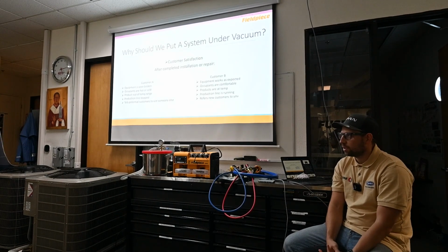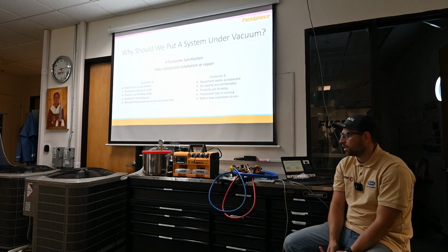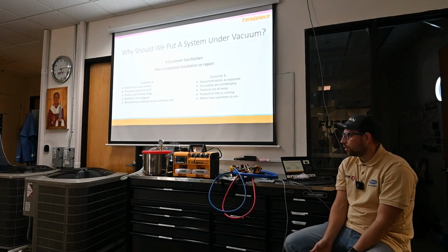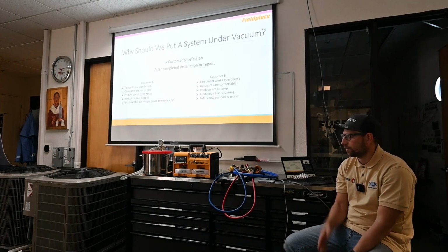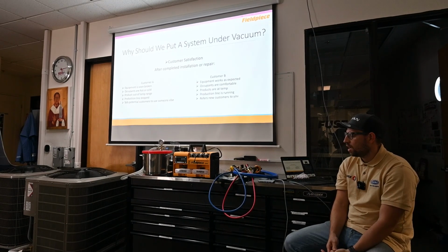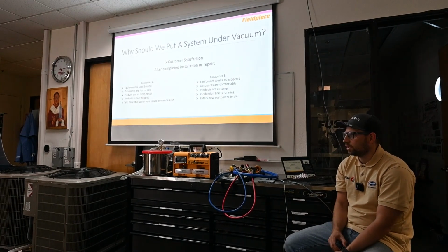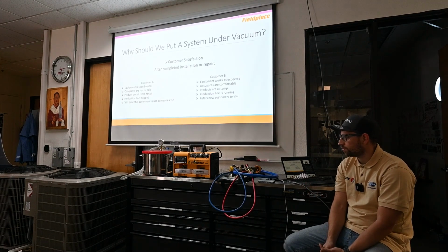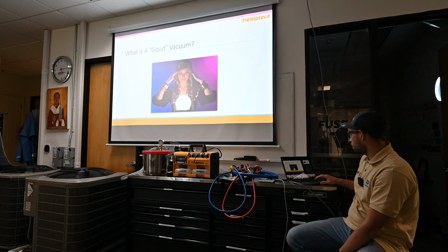The filter dryer maybe will have a restriction. The TXV valve maybe has a restriction, or the system starts to work but not with good efficiency. If we speak about AC, the evaporator coil cannot drop 20 degrees of temperature between return and supply. That's it.